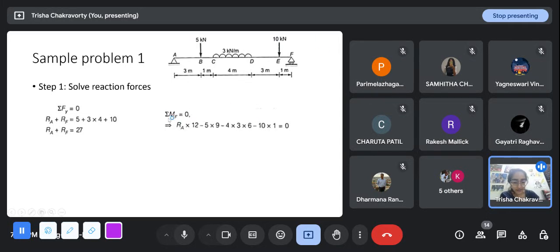So here this F represents the point about which we are checking the moment. Let's go from the left side. At this point I have a force Ra, and I have assumed it is in the positive direction, upward. And the lever arm, that is the perpendicular distance of application of this force to the point about which I am looking at the moment.